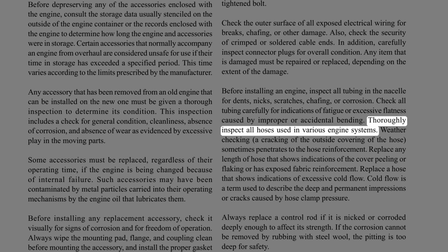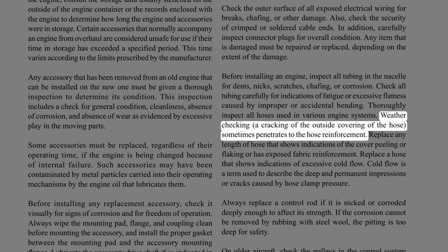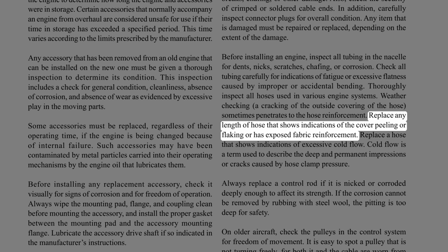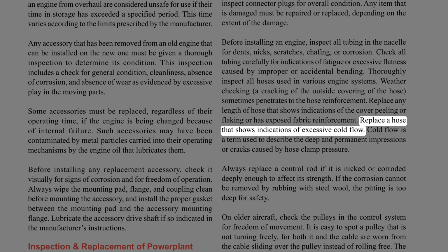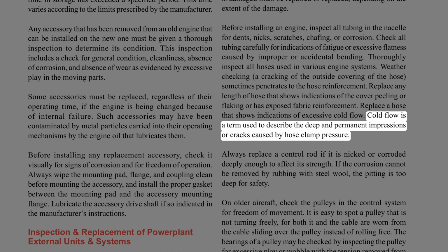Thoroughly inspect all hoses used in various engine systems. Weather checking, a cracking of the outside covering of the hose, sometimes penetrates to the hose reinforcement. Replace any length of hose that shows indications of the cover peeling or flaking or has exposed fabric reinforcement. Replace a hose that shows indications of excessive cold flow. Cold flow is a term used to describe the deep and permanent impressions or cracks caused by hose clamp pressure.